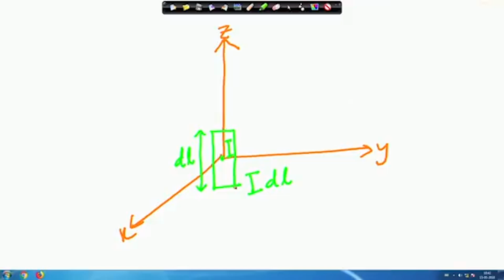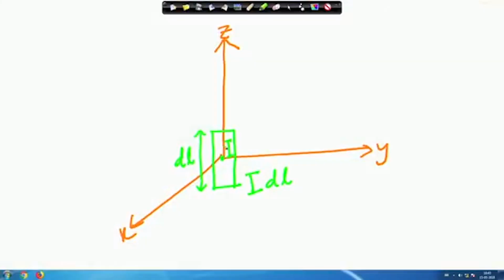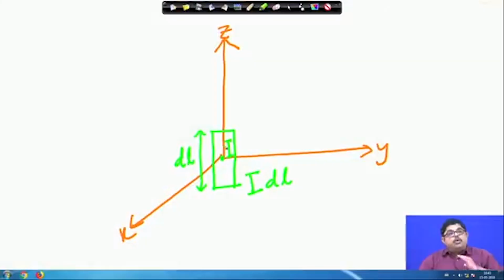that how I will put this current element. But we will see that to understand radiation this is a vital concept, because the radiation that takes place from this type of current element is present in all types of antenna radiations, and also we will be actually breaking a distributed radiator, because all radiators are distributed, antennas are distributed structures, and there they can be broken into these current elements. So, that is why this is fundamental.